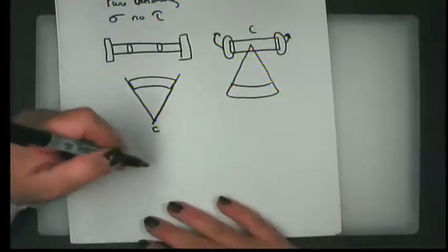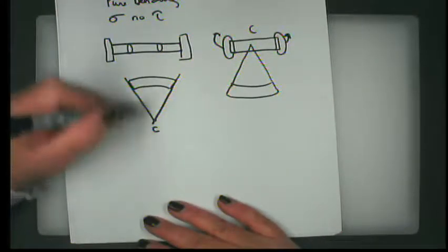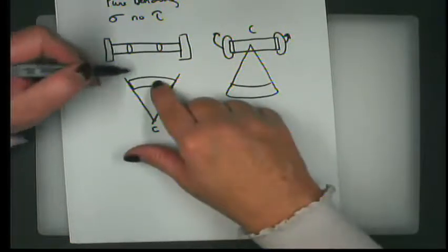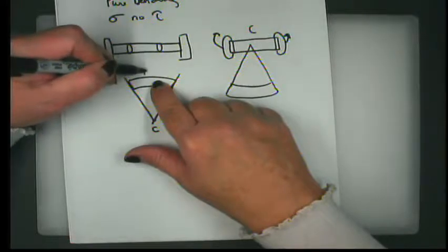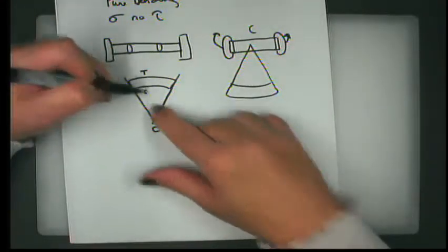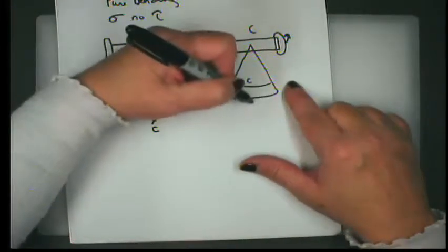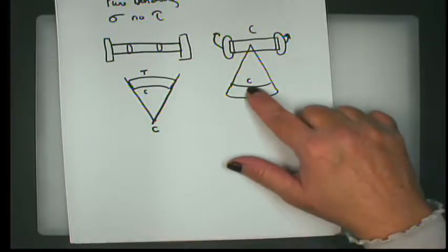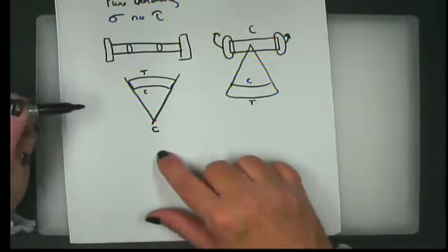So when we have a shape like this, the axis will look like this. In this case, where the top of the axis elongates, this would be in tension. The bottom would be in compression here. The opposite is true. In other words, we stretch here, that's tension, compress here, or shorten here, that's compression, and the opposite is true here.